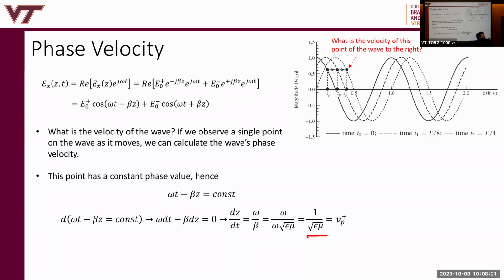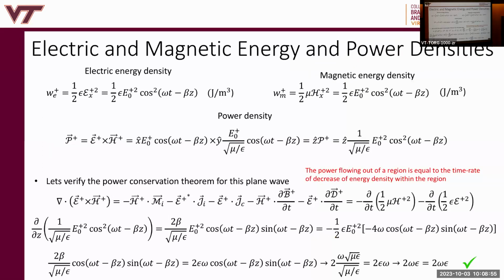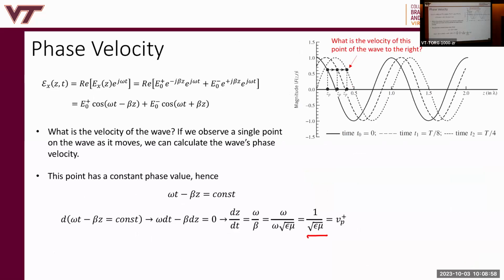So the medium has a lot of power in the electromagnetic wave. It determines the relative strength ratio of E and H, the velocity of propagation, and so forth. So if you want to slow a wave down, what do you do? Increase permittivity or increase permeability. That slows the wave down. So when a wave enters a dielectric medium, it's going to move slower. We'll see that.